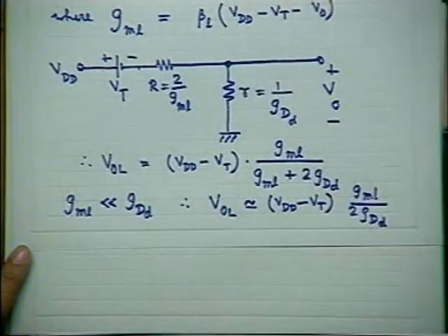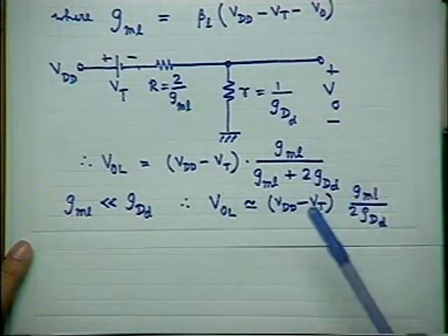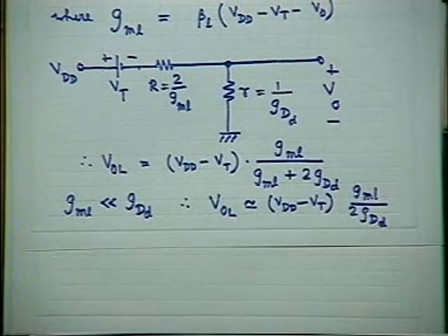Earlier, to obtain the value of VOL, you had to do many things, as I indicated in the last class. VOL is very important; VOH is obtained very simply, but VOL has to be obtained, otherwise I cannot compute the values of the noise margins. Very important for me. But now I have found an easier means to compute the value of VOL from an equivalent circuit output. This will not be that accurate because I have made a lot of simplifications, but it serves a practical purpose.